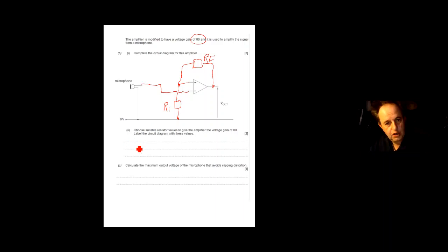Right, first thing, because it's a non-inverting, my gain, look up your equation. So you got your 1 plus your RF over your R1. Okay, so in this case, I want a gain of 80. So let's put the numbers in, substitute in. And then, if you notice, you will always tend to have two resistors and you don't know a value for either of them. So the rule is you will always choose your input resistor or your R1 to be 10K. Okay, so always choose that one to be 10K or more. Doesn't matter. 10K tends to be the value we tend to use.